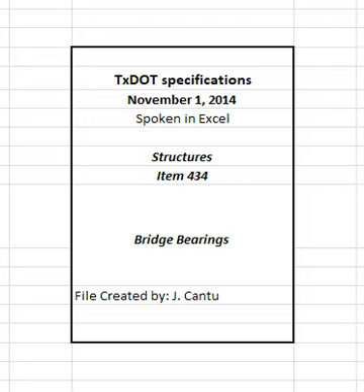Fabricate the laminated elastomeric bearing pads according to Section 434.3.1, plain and laminated elastomeric bearings. Vulcanize the laminated elastomeric bearing pad to the PTFE face steel plate. Machine the steel plate recess surface flat to a tolerance of 1/32 inches and within 1/32 inches of required depth. Bond the PTFE material to the steel plate recess surface with an approved adhesive.